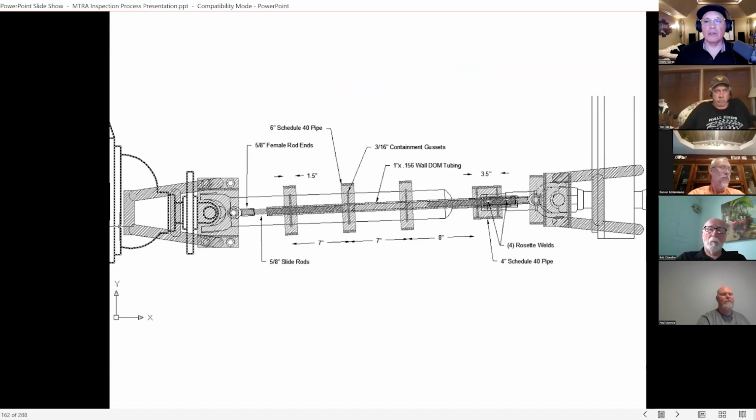Another very critical thing to watch for is the location of the smaller diameter piece that's on the stub shaft. You want to make sure that it's in the right spot, that it's capturing that stub, because more often than not, that stub where the drive shaft narrows down with the slip that goes into the slip joint, that's usually the failure point. When the drive shaft gets out of balance for whatever reason, something hits it, or a U-joint fails and it gets into an oscillation, that point is usually the piece that breaks.